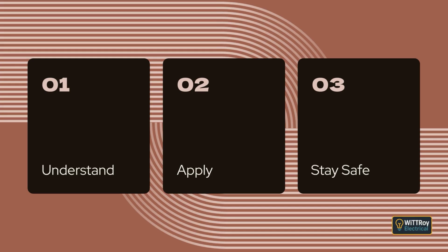Clause 2.3 Control of electrical installation. Clause 2.3.1 General. The installation must have devices that allow safe switching, safe operation, and safe maintenance. These devices include isolation switches, emergency shutdown switches, mechanical maintenance switches, and functional switches for normal control. If one device performs more than one of these jobs, it must meet the rules for each function.